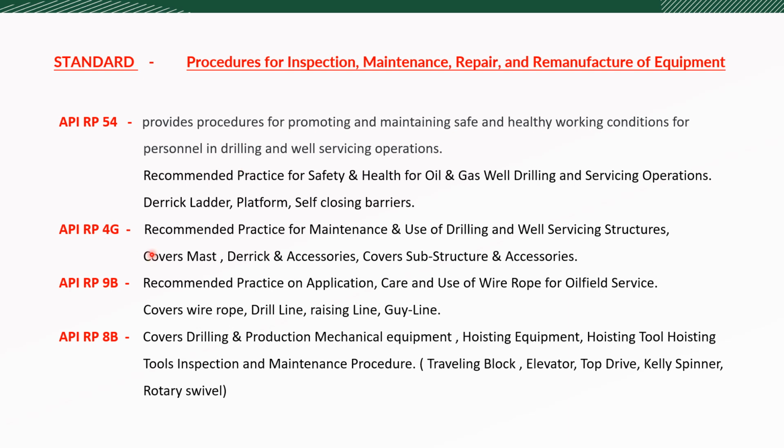There are a huge number of API standards, but here I have collected the API standards which are important to learn for a rig safety officer. Now let's see some standards. API RP 54: whenever we hear this standard, it is particularly for maintaining safety in oil and gas drilling and well servicing sites.